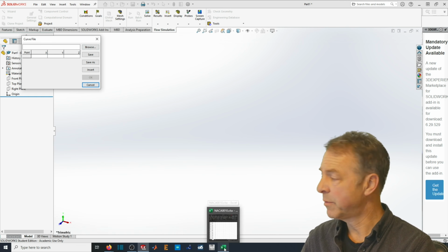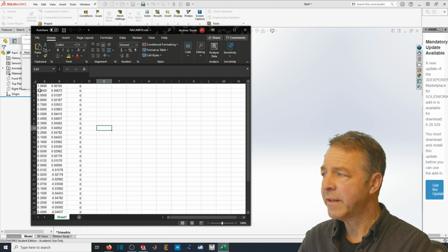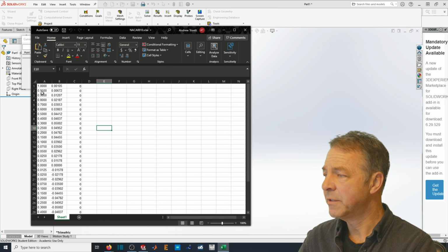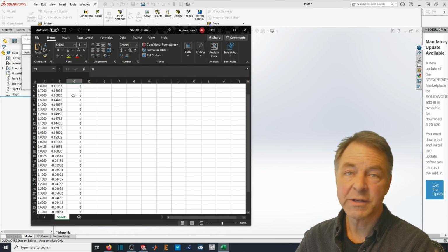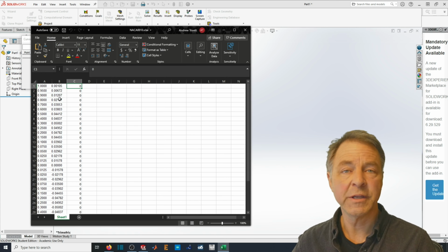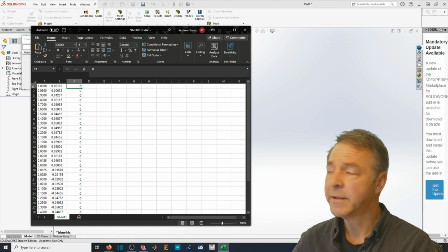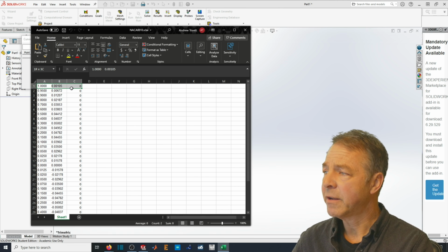Now what I've done before this video is I took that data that I just cut and pasted, and I put it in an Excel spreadsheet where I've got X, Y, and Z. Now, because of SolidWorks' necessity to have it a three-dimensional curve for the input, I had to add 0 for Z. That's fine. And now I've got these three parameters.